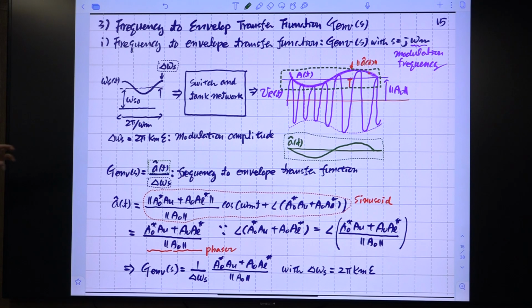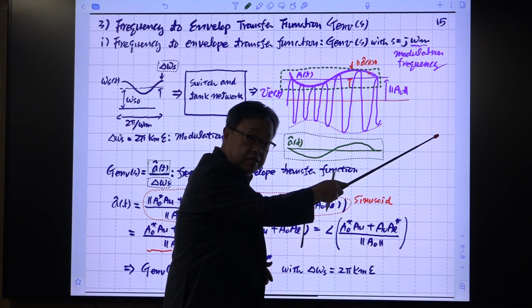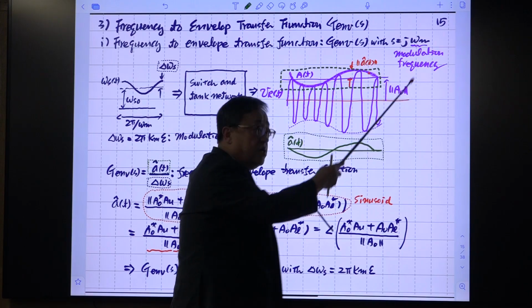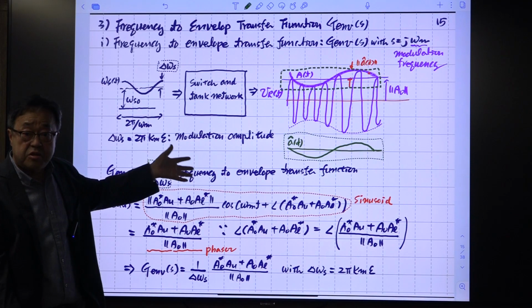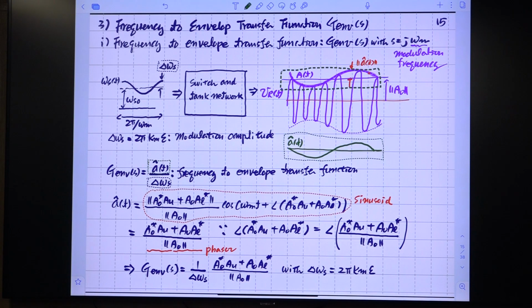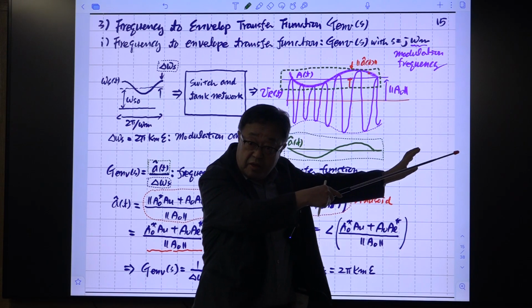And we have our filter inductor and our filter capacitor and load resistance. This corner frequency is way below this one. This is very high frequency dynamics, because the circuit components in the resonant tank are very small, and the circuit components in our filter are very large, maybe 100 times, something like that. So we have a huge separation. So this only specifies the high frequency dynamics, and for the low frequency dynamics, we just incorporate the low frequency dynamics of this output filter, okay?